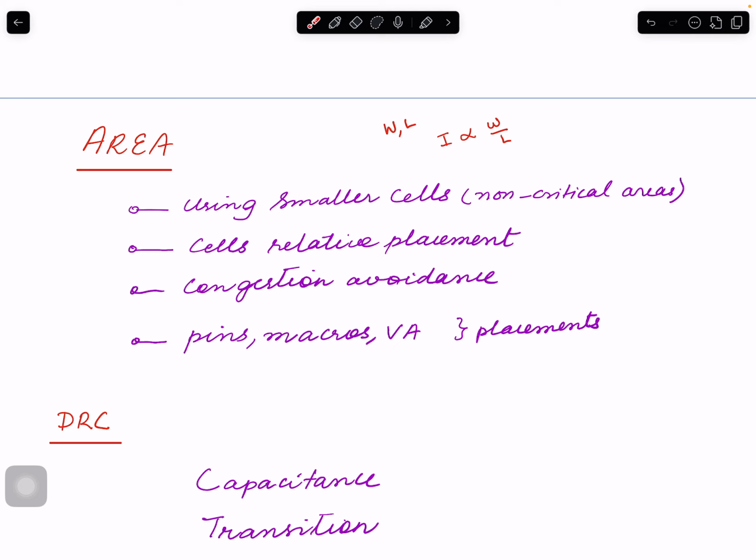You can help the tool if you already know your design and the flow of the data. You know certain ports, or what I'm calling here pins, of the design need to be on this side, because they go to SRAM first, or your SRAMs are placed first, and then your other logic follows. So you need to understand the higher level flow of data in your design, and based on that, you can drive floor plan and hence area.